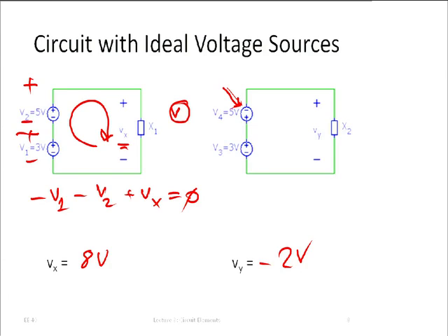Okay, this element here, like X2. Okay, so you need. I can. That would be a really unfair question. I can ask you what is Vy, right? Because I told you where the plus and where the minus is. I could also ask you what is Vz. I could ask that, and you would get plus 2 volts, right? Because I drew the symbol the other way around. But I could not ask you just what is the voltage, because the answer could be it's 2 volts or minus 2 volts, right? So whenever you mark up your schematic, you have to choose signs.